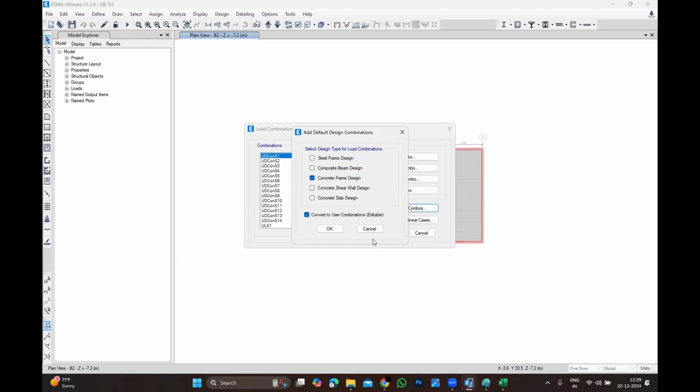So you don't need to spend the 1 hour, 1.5 hours to create all those things. In the master file, you can feed in as many section sizes as you like, from 200 by 600 to 200 by 800, 300 by 600 to 300 by 800, 400 and so on. Then when you fine-tune the model, whichever section sizes you haven't used, delete them. But keep the master file.